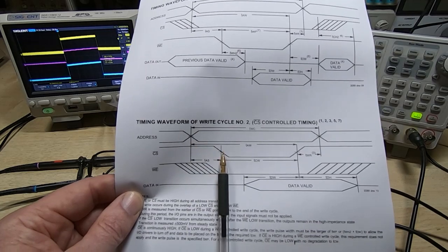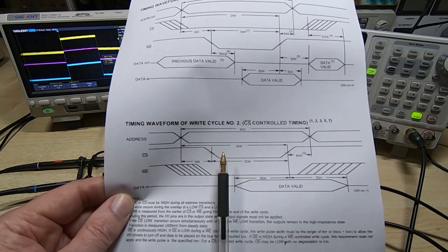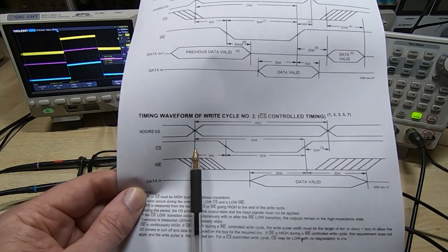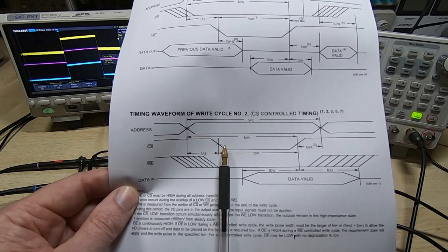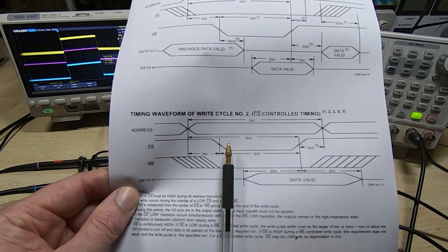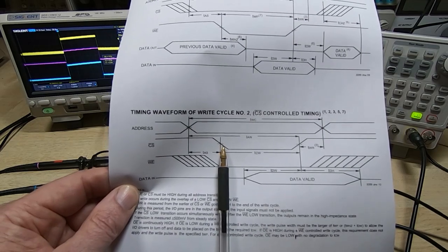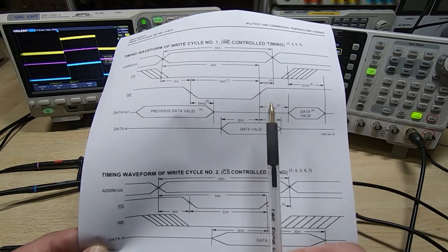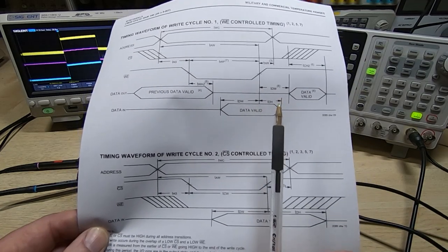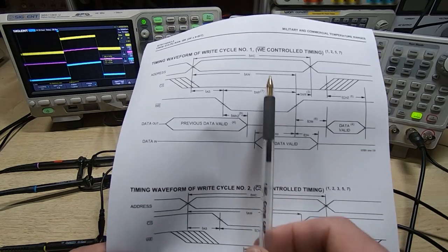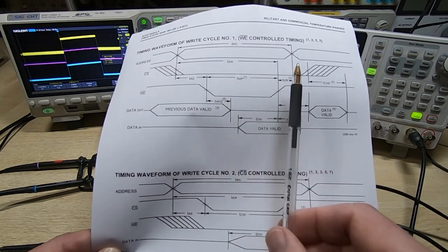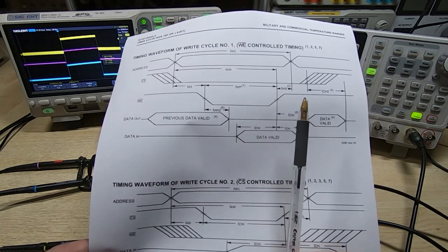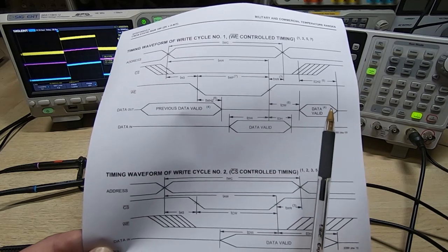But the point here is, if this edge is being controlled through a string of TTL logic gates, then this time is meant to occur within a certain time window, and if the device starts failing, this can occur at the wrong time. Or worse still, the write and chip enable lines, data valid point and the addressing can all be out of sequence, in which case you can end up writing to the wrong address or more than one address, as I demonstrated in the previous video.